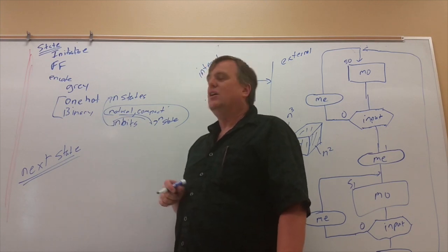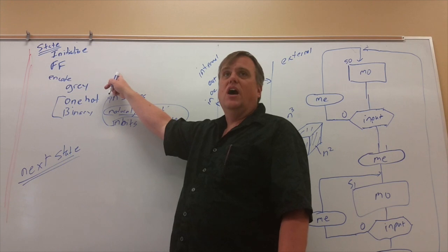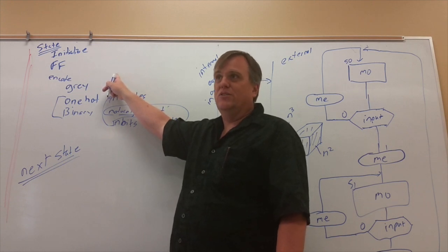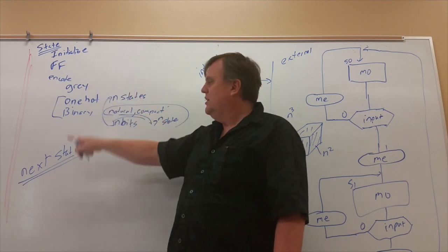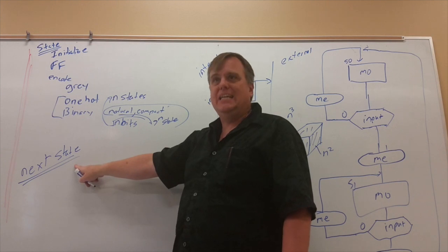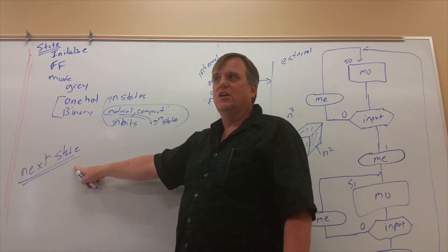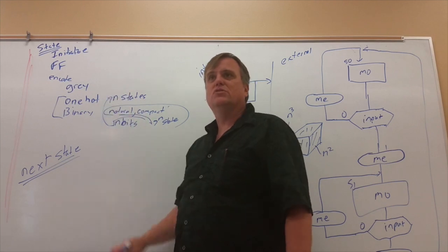Synchronous. Remember our danger? This one needed non-blocking commands, and it needs to be edge triggered. This one needs to be triggered on any event, i.e. asynchronous, constantly going, and it needs blocking. I can't mix the two types.